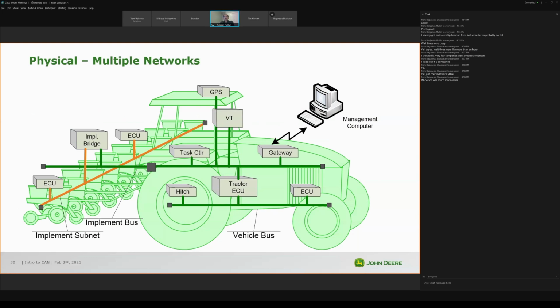You also need to update the software to understand the CAN-FD frames and to handle the additional data that you can get in that. And also, of course, the memory, because you have more data coming in the same time frame, so you should be able to handle that.